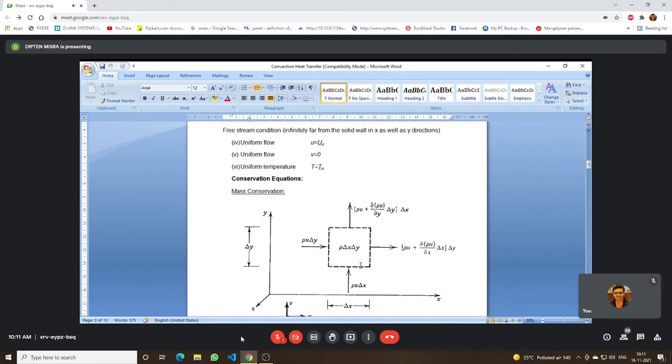Now, in the flow field given by along the x direction, y direction, and z direction, we take a two-dimensional control volume because we are considering that the flow is two-dimensional in nature. And along the third dimension, things are uniform, it doesn't change. So what we can do is that we can take a unit depth.